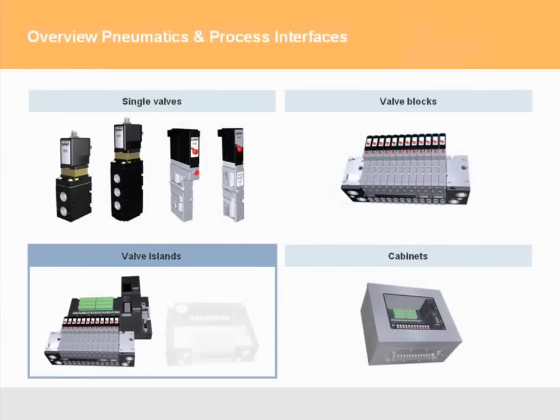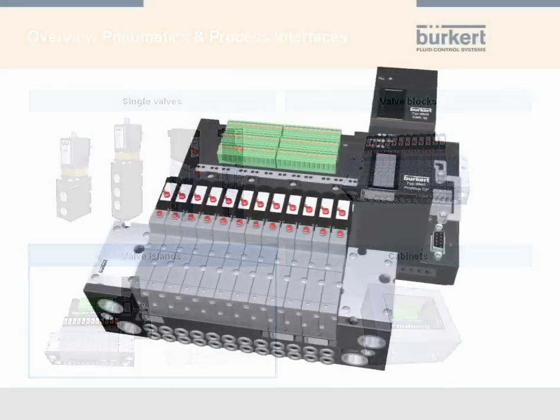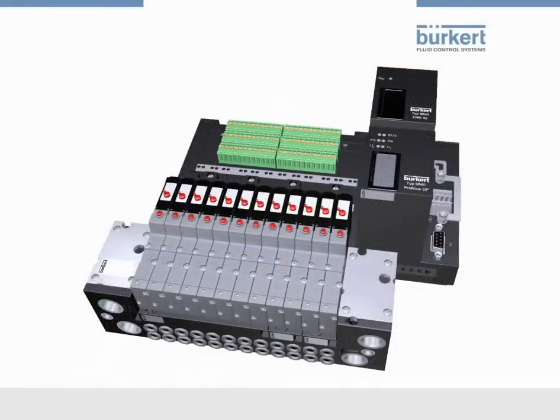Valve islands and automation systems are constructed in the same way as valve blocks. In contrast to these, they offer a common electrical actuation of the valves. Common connection, multi-pin or Fieldbus interfaces, for example Profibus or Ethernet, may serve as the communication module. But what is a Fieldbus? Tom will lead us through a short excursion into Fieldbus techniques.